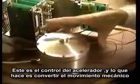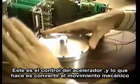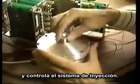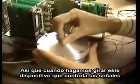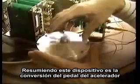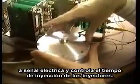This is the accelerator control, and what this does is convert the mechanical movement of the gas pedal to an electrical signal which is brought into the system here, which controls the injection. As you would turn this device, which controls the signals, you'll notice that it would also be controlling the injectors as the same function. So this device right here is the conversion between the gas pedal and an electrical signal which controls the injection time of the injectors.